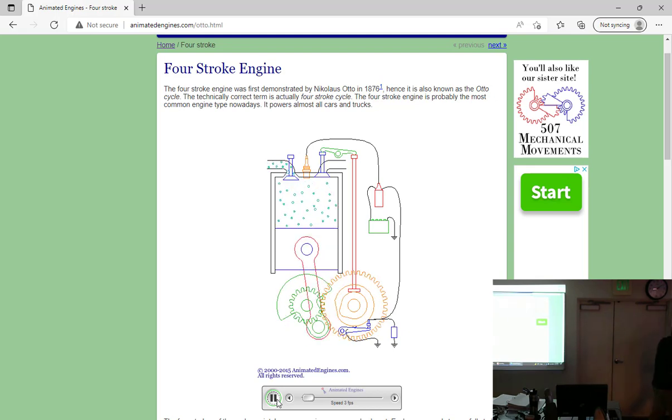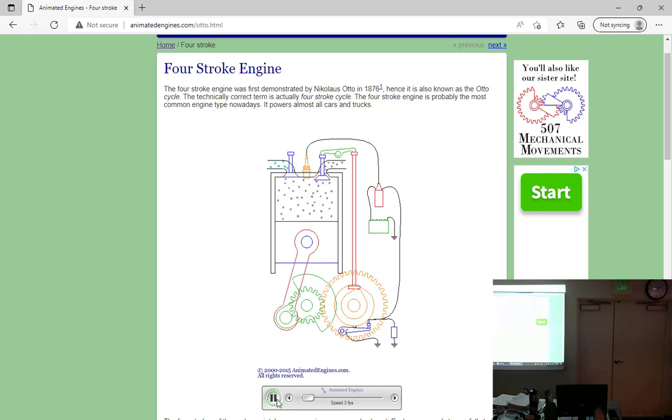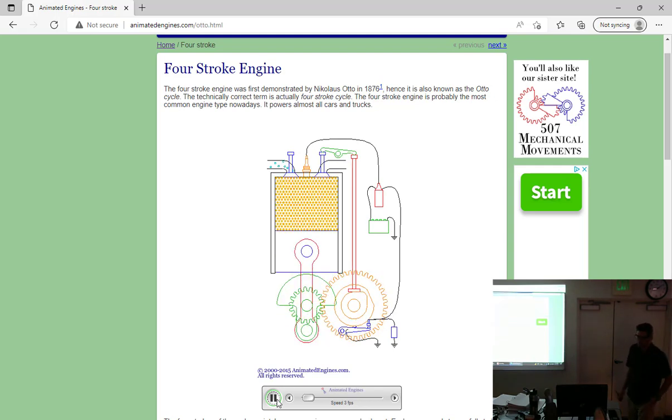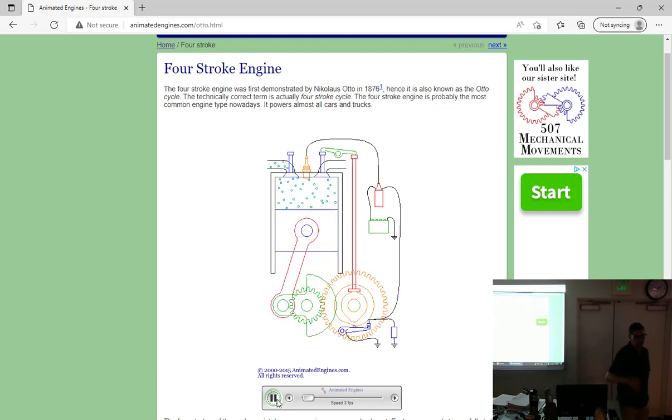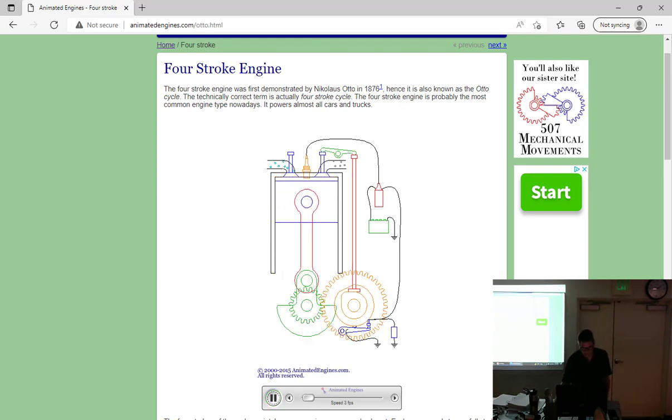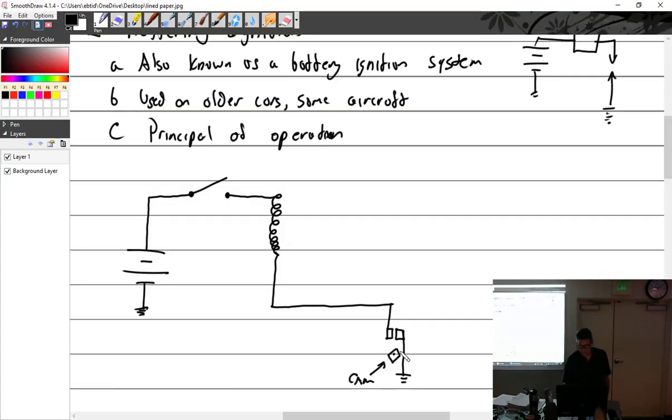And you can imagine if you just threw this together and one of the valves opened at the wrong moment, you'd have a big problem. Right? So it's all got to be timed. That's your engine timing right there. Because the camshaft is the brains of the operation, and it has to know when the valves open and close, you can run this little cam that I have here, the breaker cam, off of the camshaft. So it usually runs off of that in this ignition system.